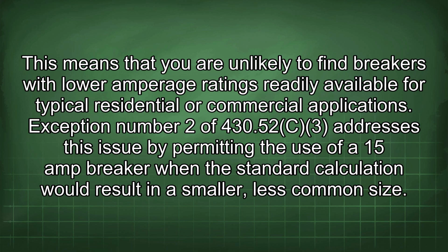Exception No. 2 of 430.52(C)(3) addresses this issue by permitting the use of a 15 amp breaker when the standard calculation would result in a smaller, less common size.